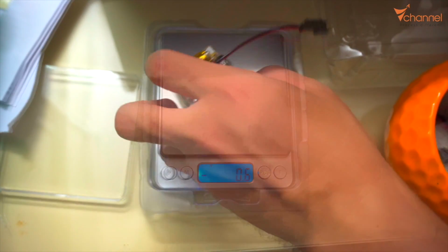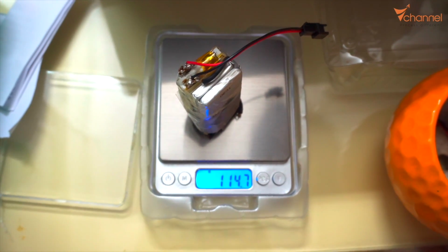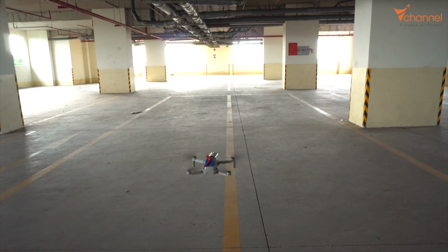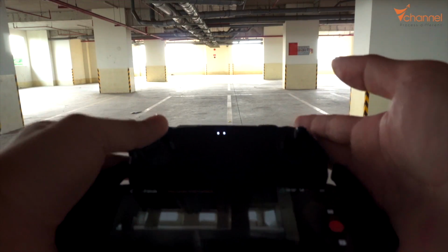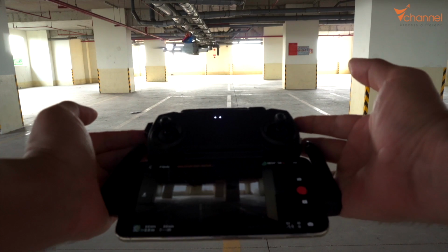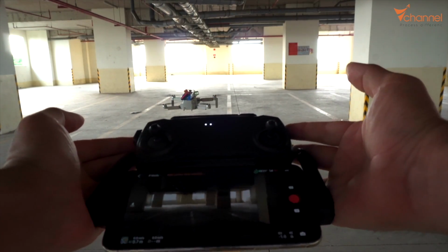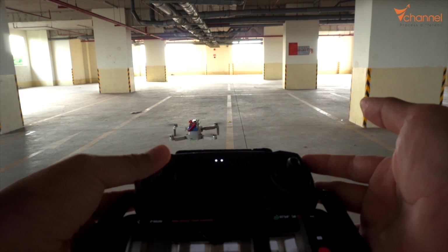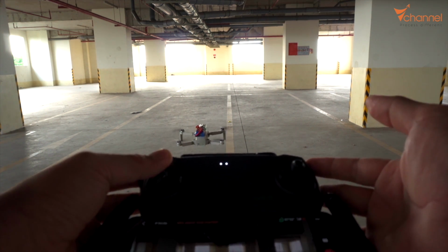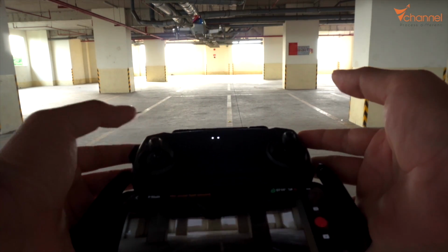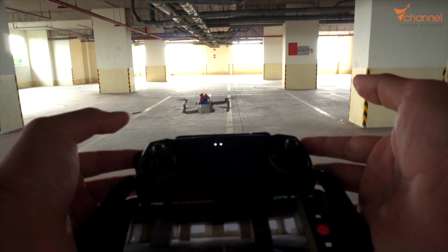One important thing is safety. Because manufacturers always design superfluous power. When flying, the drone will fly in unfavorable conditions such as strong wind. In that case, the motor will have enough superfluous power to fight against that wind. When we design such a heavy battery, it will not have enough power to fight against the unfavorable wind. There will be a risk of it going out of control.